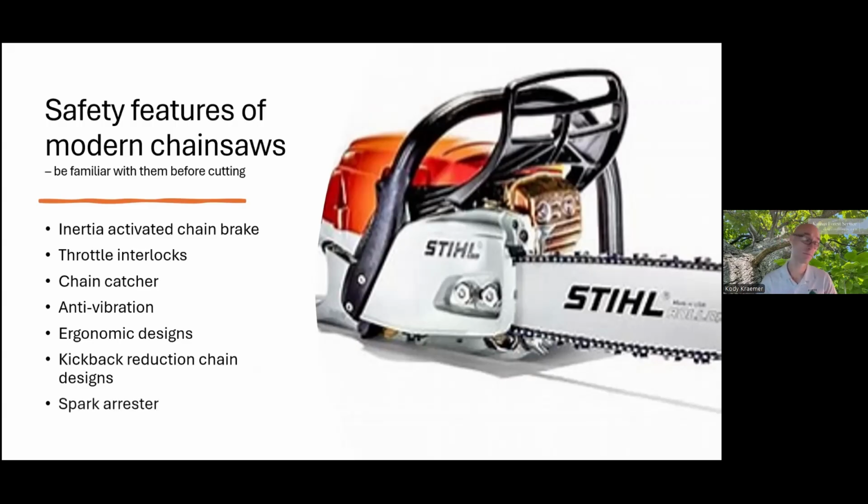And then in the world of wildland fire, it's really good to make sure your spark arrestor is working properly, is not plugged up with carbon, and it's something to check. So if you aren't aware of what some of these features are on your saw, I would highly encourage you to look through your saw manual and get to know your saw a little bit better and be aware of all of these things.